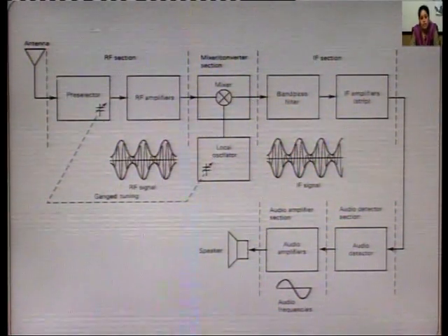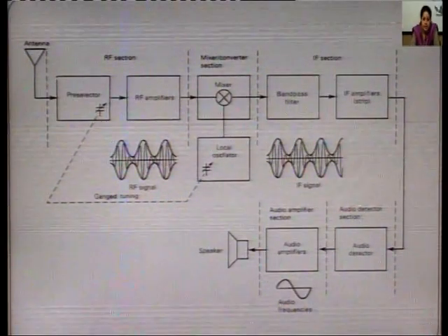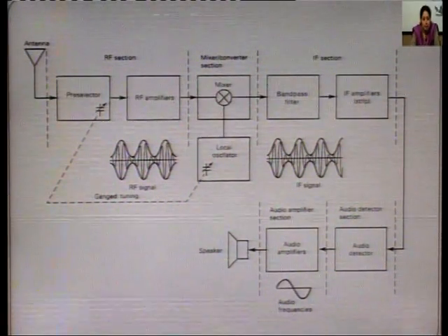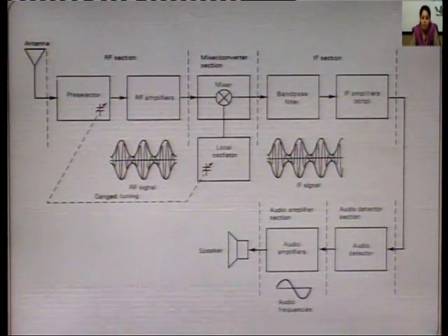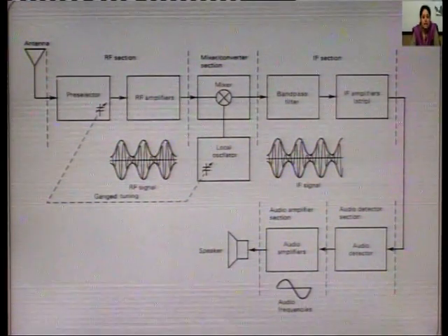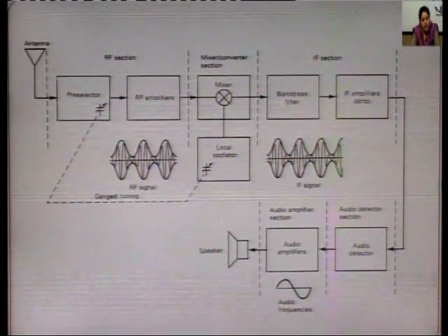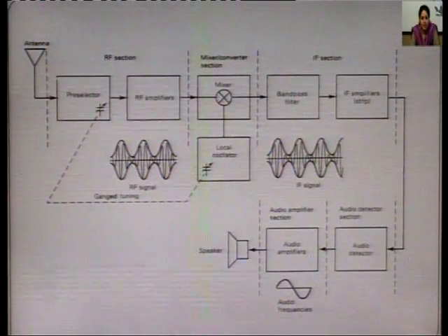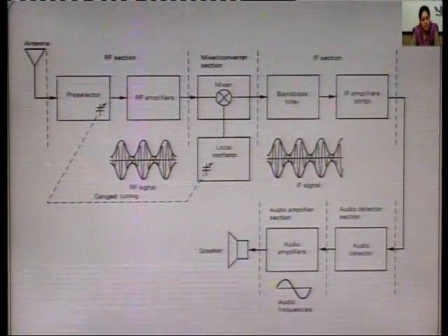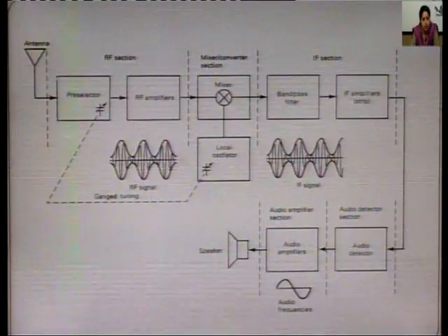So the harmonics produced will be F0, Fs, F0 plus Fs and F0 minus Fs. But at the mixer only the difference component is allowed to pass further, rejecting all other three harmonic components. That is, only F0 minus Fs is allowed to pass further. The mixer bandpass filter will allow only the difference component.